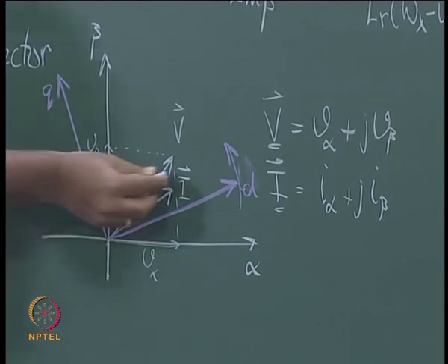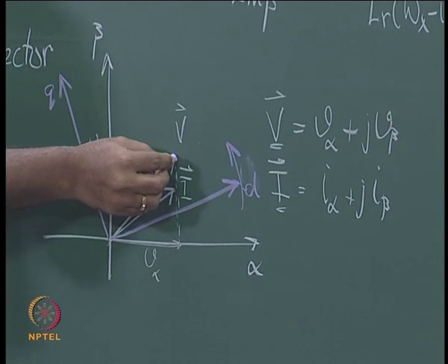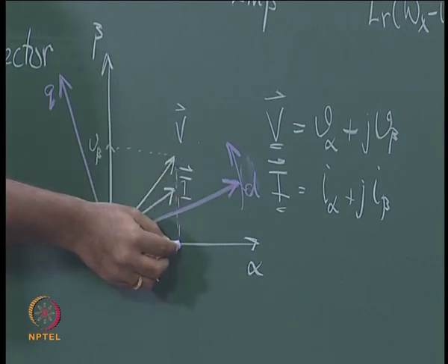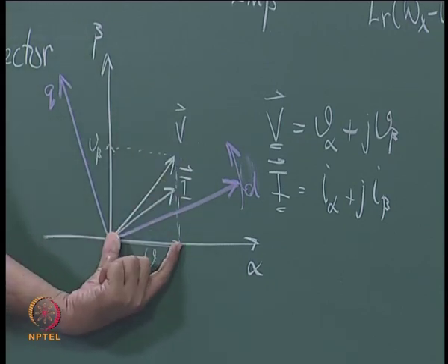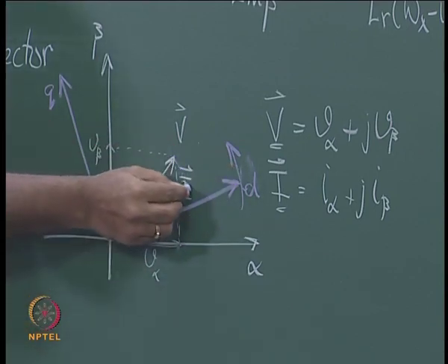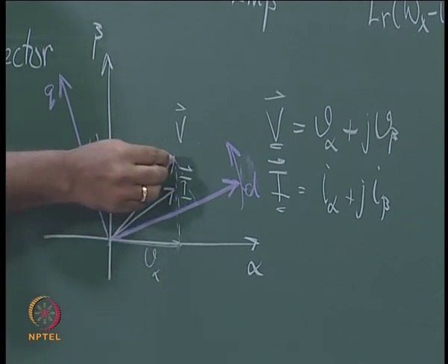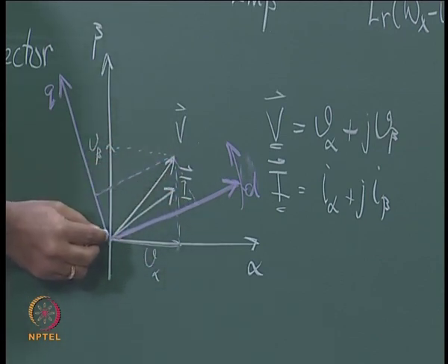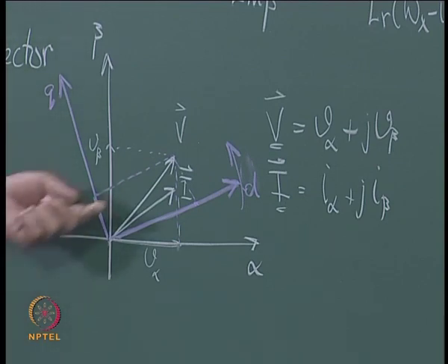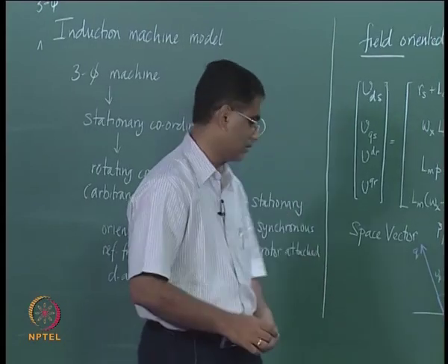in which case now you had a V alpha term as from this vector. If you then take the alpha axis part, this is your V alpha, but on this axis you will have to take a component here. This then becomes your length Vd, and similarly this component becomes your length Vq. So depending on the axis you will then have Vd and Vq, depending on where they are located.